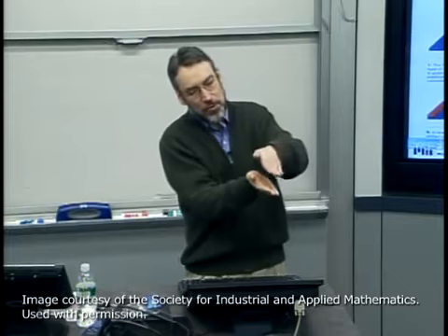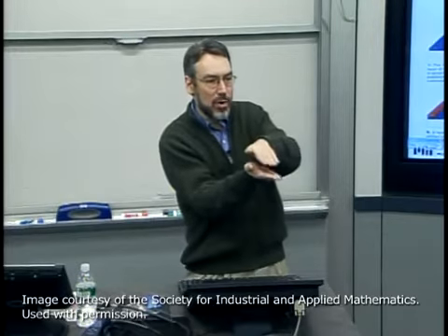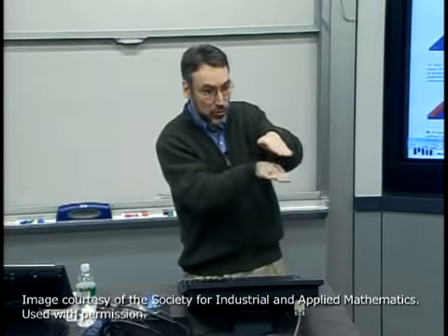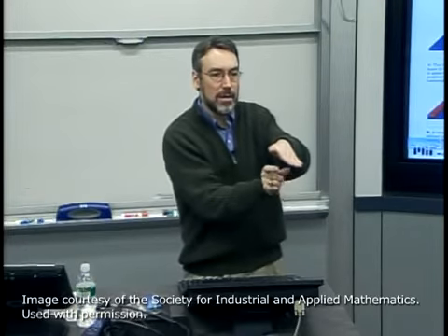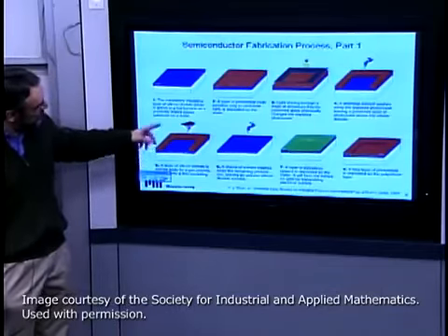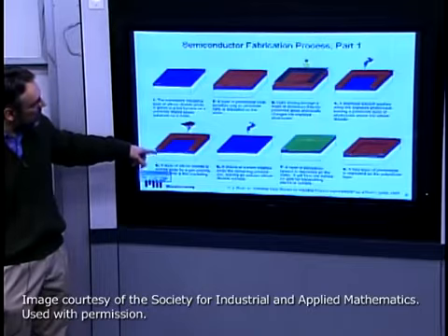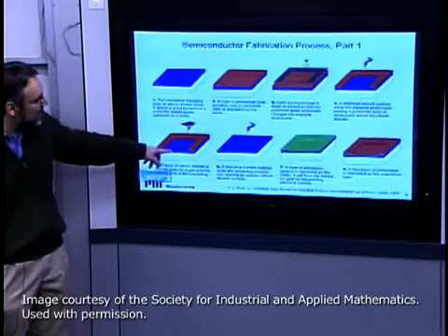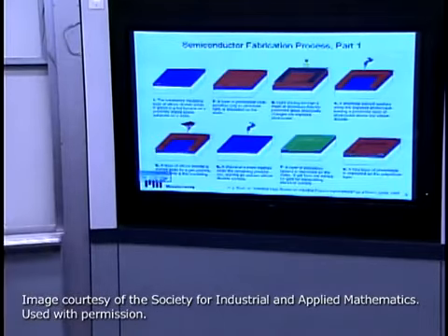And the reason is the closer I can get my 2 plates of that capacitor, the more capacitance I have, and the more control I have of the silicon surface. Okay, so the harder I can turn the device on, the more current I can flow per unit area, and so on. Okay, so in this process, apparently we're etching from about a half micron, 5,000 angstroms, down to we might be at 100 angstrom or below remaining gate oxide layer, which in a modern process is really what you want. Everybody happy with that?